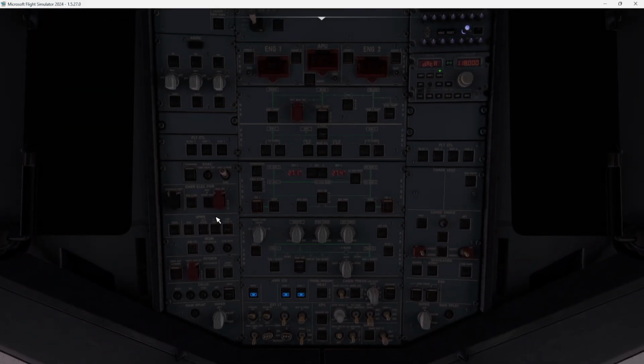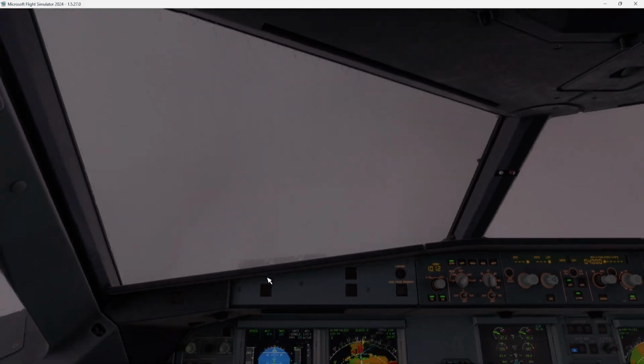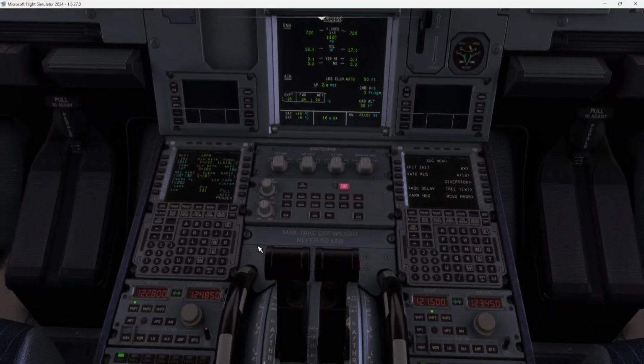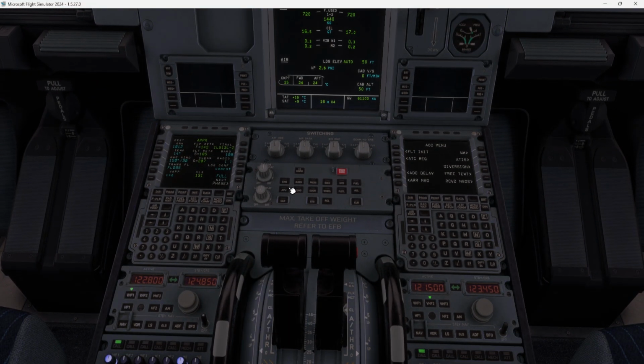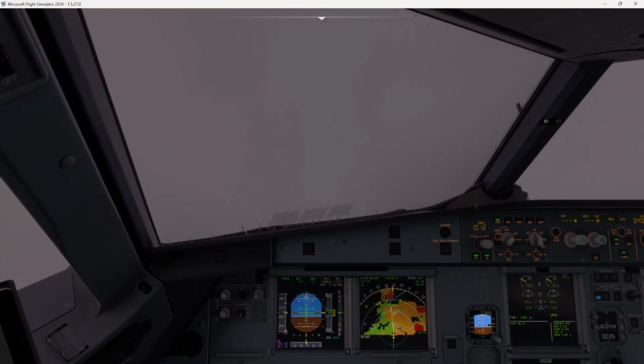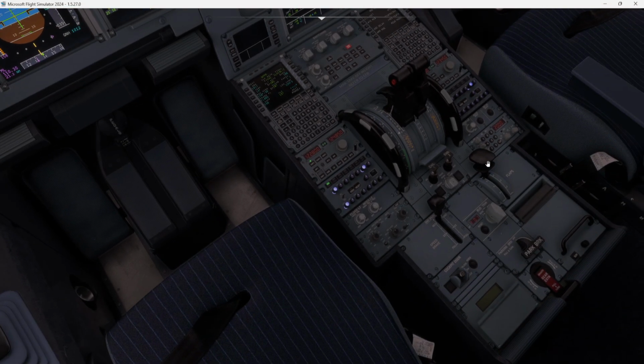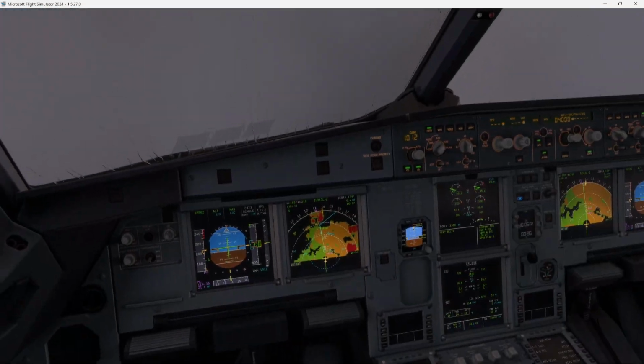So let's go to the GPWS and put flaps 3. It gives us approach of 147. I'm going to add 3 knots because the wind is not looking good, so 150. Speed checked, flaps 1. Let's arm speed brake.